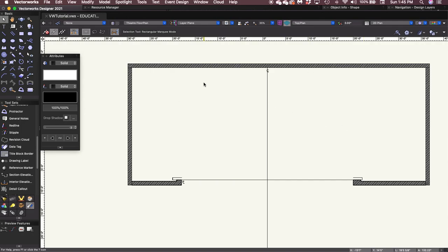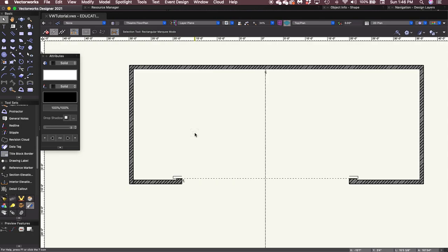Okay, we still need to change the line weight on the architecture that we drew. So let's go ahead and select those 3 walls that we put in. Again, their line weight is 2. We don't want that. We want it to be 20, which will match what we did for the proscenium. So by selecting that, now all of our architecture has exactly the same line weight.